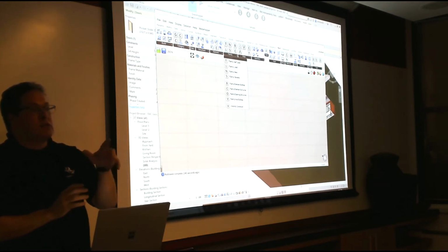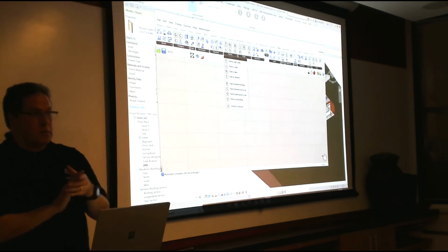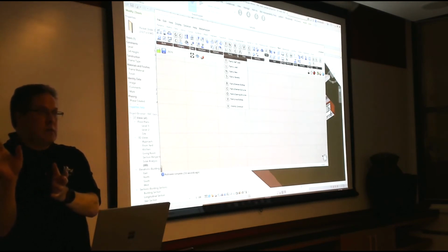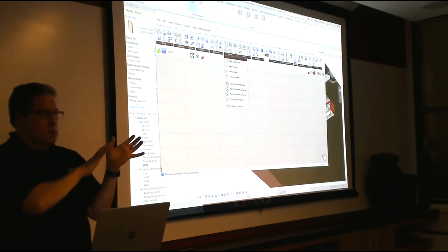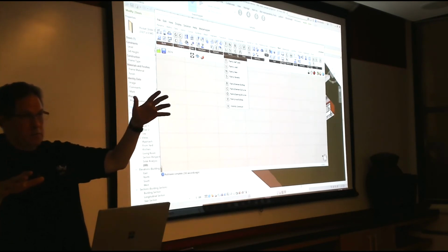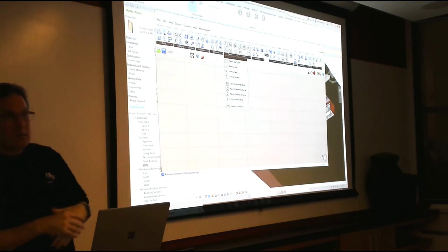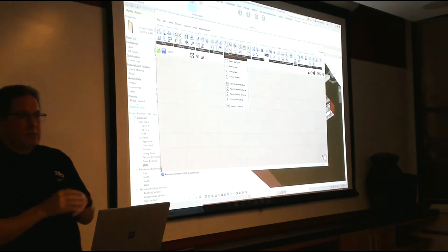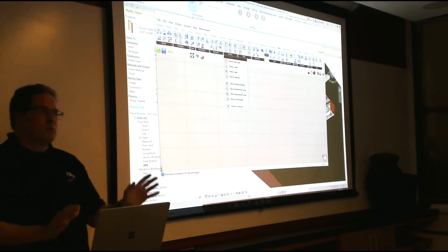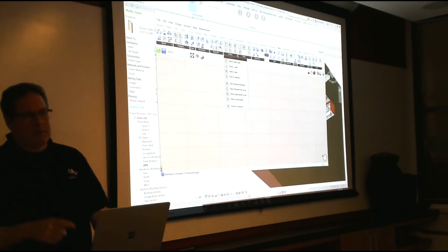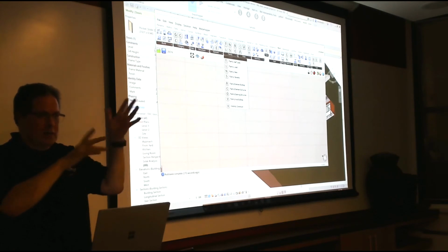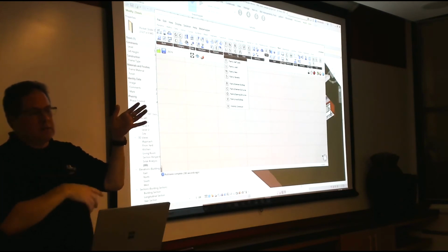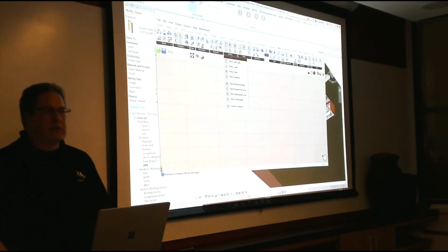The other thing that I've seen is don't rationalize too early. We have people that are trying to rationalize in Rhino, and then they're pushing all these arcs into Revit. Really, probably what should happen is you push your beautiful big surfaces into Revit, and then you rationalize in Revit. That's another workflow that's starting to take hold in this process. Can you imagine having a big roof with thousands of different arcs? Revit's going to tell you, forget it, I don't want a big roof with 1,000 little arcs in it. If you just put the big beautiful surface in there from Rhino, and then you have adaptive components march along, then Revit takes it.